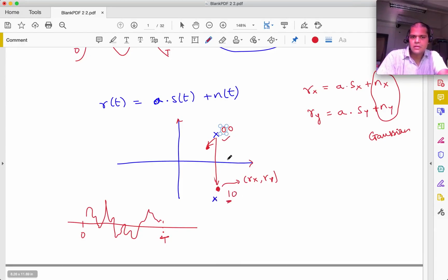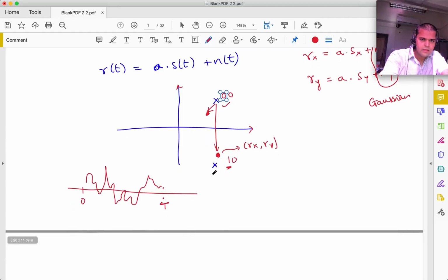But if this was in the first quadrant, we would say 0 0 was transmitted. So if I make a mistake, maybe the noise was too much and it pushed it over here, I would say instead of 0 0, I would say that 1 0 was transmitted. And luckily this bit was not received in error. Though I got the wrong constellation point, I still guessed this correct.